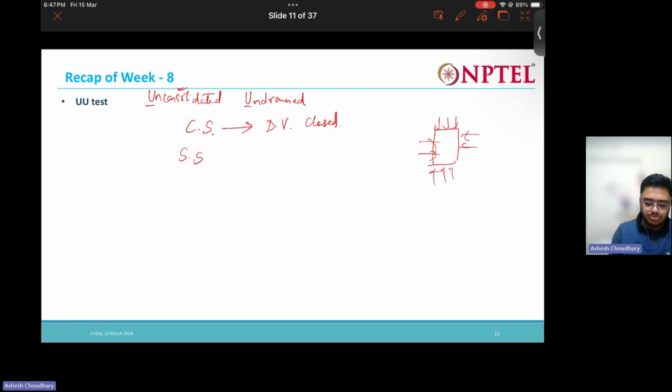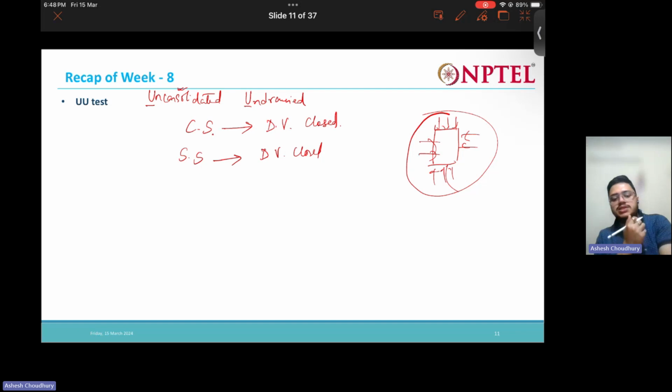After that you do the consolidation stage. In the UU test, we do not allow drainage or the release of pore water pressure. As we do not allow drainage, the first stage is known as unconsolidated, since we are not allowing consolidation to happen, right? Then we start the second stage. In the second stage also, we keep the drainage valve closed. So as there will be shearing, pore water pressures will get generated.